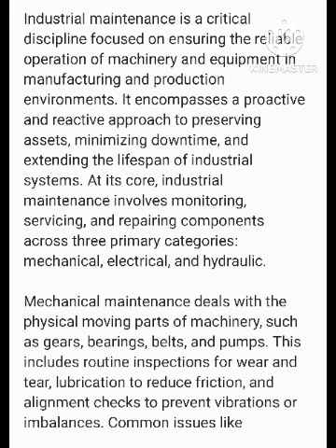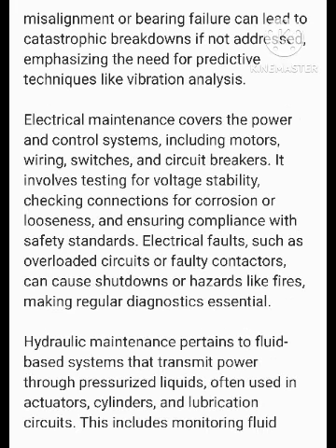and hydraulic. Mechanical maintenance deals with the physical moving parts of machinery, such as gears, bearings, belts, and pumps. This includes routine inspections for wear and tear, lubrication to reduce friction, and alignment checks to prevent vibrations or imbalances. Common issues like misalignment or bearing failure can lead to catastrophic breakdowns if not addressed, emphasizing the need for predictive